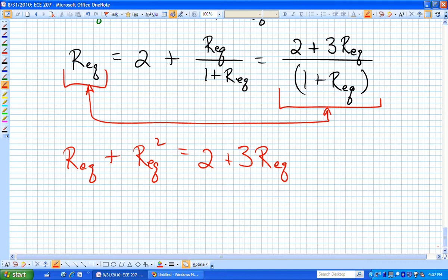So you're still stuck on why I said they were equivalent, right? The question is, in the original drawing, how come you could conclude that those were equivalent? And yes, your phrasing is the correct answer. They're equivalent because it doesn't matter if you add another 3 resistors on to the right-hand side, you're not going to change anything because it's infinitely long. And so infinite plus 1 is what?